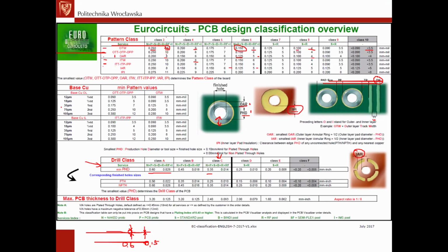Actually, another important thing that you have to analyze and choose before you go further with a design, before you even start the design, because these classes, the proper class and all the dimensions defined within a class, you really must know before you start a PCB design. This is really a must. I would even say you mustn't start before you settle the class, settle all the dimensions, before you know all the limits for the technology that you will use.